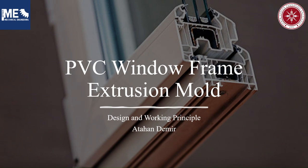In this presentation, I will give a technical overview of the extrusion mold used in the manufacturing of PVC window frames, focusing on both its design and working principles. PVC window frames are produced by profile extrusion, which is a continuous manufacturing process. In this process, the extrusion mold, also referred to as the die, plays the most critical role because it defines the final cross-sectional geometry, dimensional accuracy, and overall quality of the product.